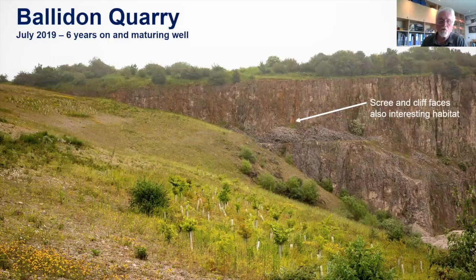It's the other side of the quarry. Again, this is 6 years on from a slope like that. Just what we would call scalpings. Things are growing. Scalping, to take the head off, is the first process in quarrying. You run all the rock over a 40mm or a 75mm screen and take out what is the weak, fissile rock, clay, small particles, which tend to have more nutrient, more ability to absorb water in there. So that's 6 years on.